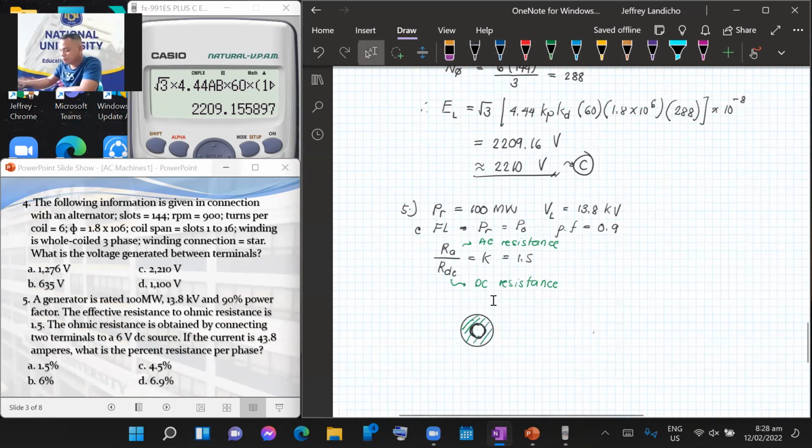If you notice, the effective area of our conductor is only this. The center is not included, so the conductor behaves as if it were hollow. The area is then smaller compared to the initial complete area. We know resistance is inversely proportional to area, so the resistance increases because the equivalent area for electron flow decreases, due to high frequency. That phenomenon is known as the skin effect.